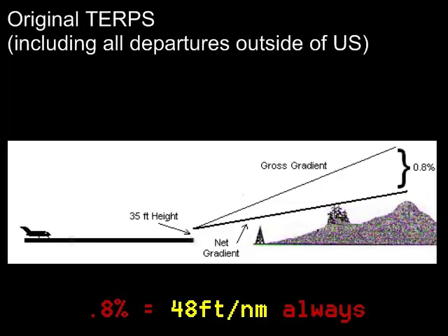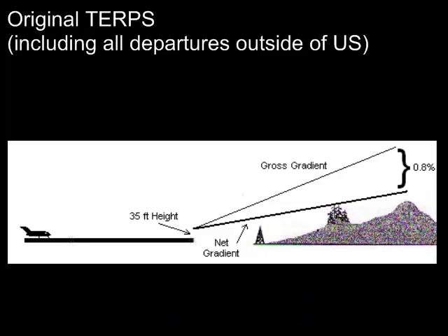When this type of departure is used, there must be allowances made for the close-in obstacles by raising the runway end crossing or reference height from 35 feet to 70 feet. The OIS, or net gradient, is then easily established by simply reducing the published gradient by 0.8%.